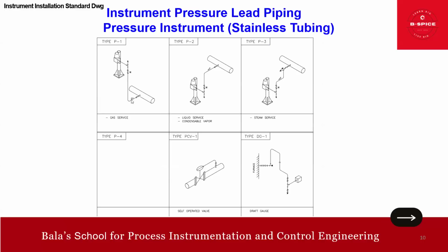So this is just a single tapping and gas service. So this is on the top, then liquid service, this is on the bottom. Okay. Then this is the steam service. This is also on the bottom. Okay. Then you have this PCV1, right? This is actually for a self-operated valve, a self-regulating valve. This is the typical look and feel.